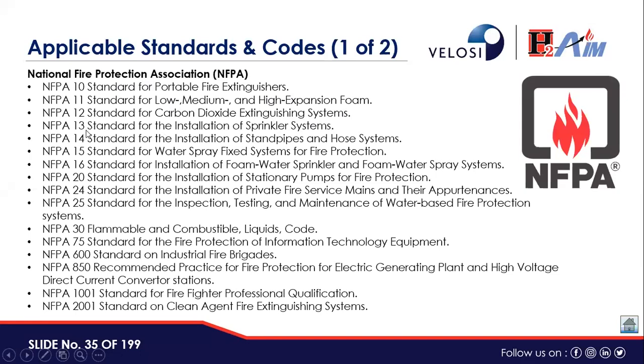Then NFPA 13 and 15 are for water sprinkler systems and water-based layouts and systems. Then NFPA 30 is a more common one, the flammable and combustible liquids code, which is used in the hydrocarbon industry. Then there is NFPA 12 for carbon dioxide, and NFPA 2001 is for clean agent firefighting systems. So these are the standards available. If we have access to these standards, they are very user friendly and we can easily follow their guidelines.